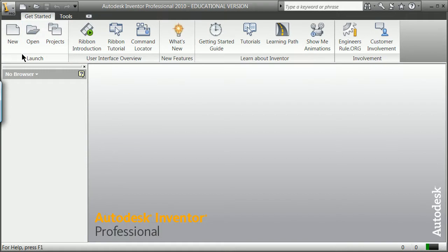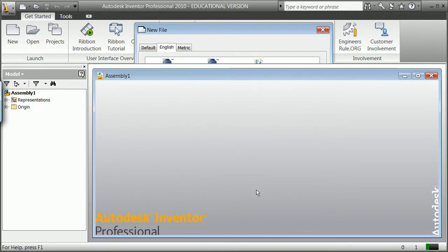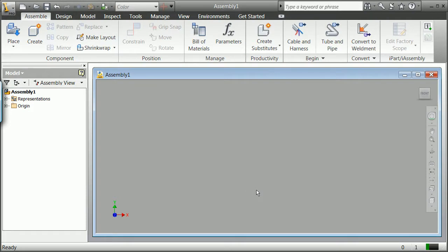And we put things together in an assembly. So we're going to go with a new assembly here, pointing out finally and emphatically the way to go about doing this once you get done with the simple work of a couple of pieces is to use sketch blocks. Draft things in AutoCAD in 2D, make sketch blocks of them, and make parts of the sketch blocks. And we'll do a series of videos on that.